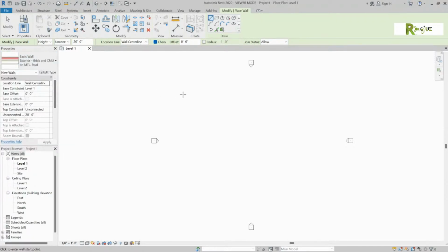All right. So generally, Revit wants to draw what, clockwise or counterclockwise, Eric or Misty? Do you remember? What you're going to try to do is we're going to try to draw the footprint of a building in between those 4 little symbols that are on there. Those are elevation markers, which we will end up getting into, but somewhere inside of that middle, I want you to draw the footprint of your building. So when you start drawing, go ahead and click on your screen.